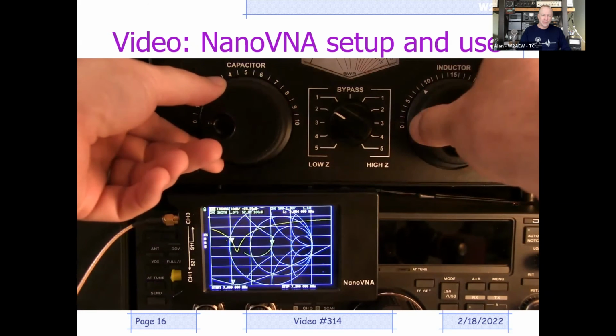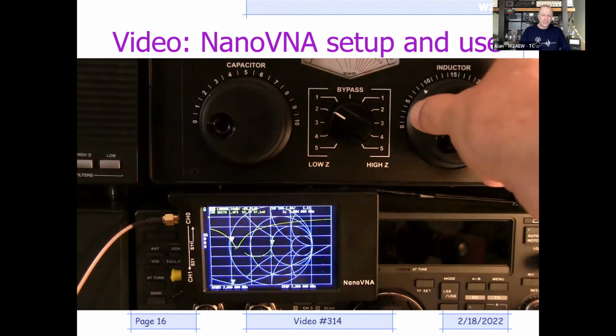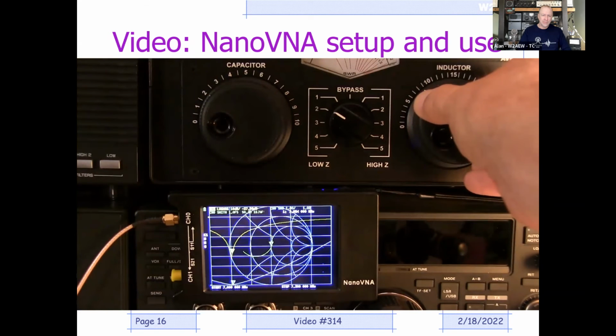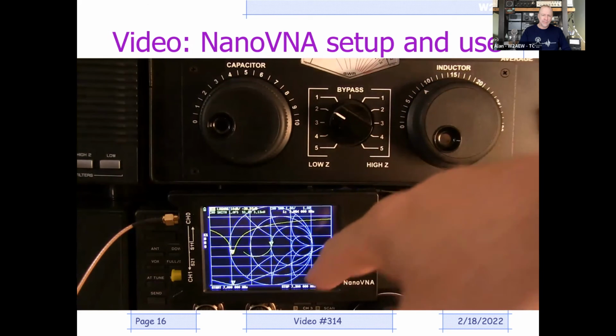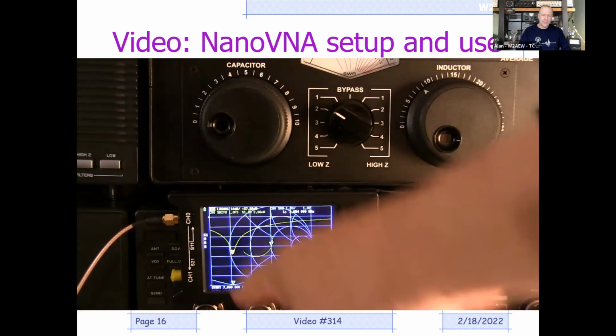So you can see with just a little more fine tuning on the controls of the tuner, I've got myself pretty darn good at my desired point right there. SWR is about 1.02. I'm sitting right at the center of the Smith chart.